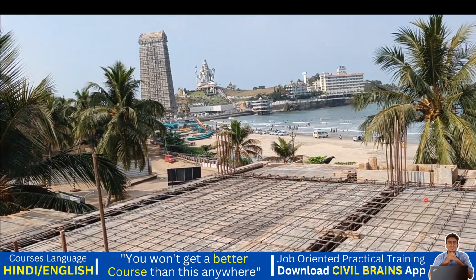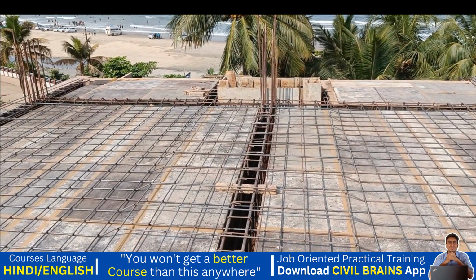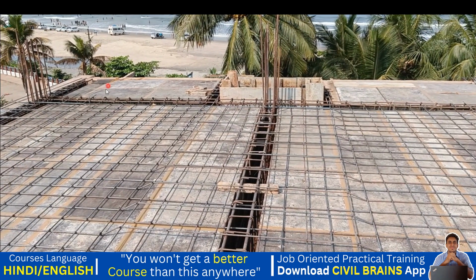So I'll go a bit forward. So here you can see all the things have been done. I want to tell one more thing. Now if I stop it here, see, this is my cantilever portion. So in the cantilever portion I need to provide the top steel. So top steel I'm going to provide in this direction. In the same video I'll show you again. So I'm going to provide a reinforcement here, so that will be my cantilever steel.